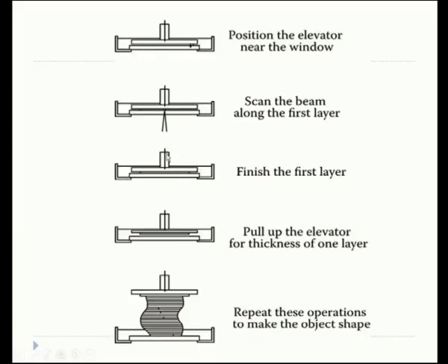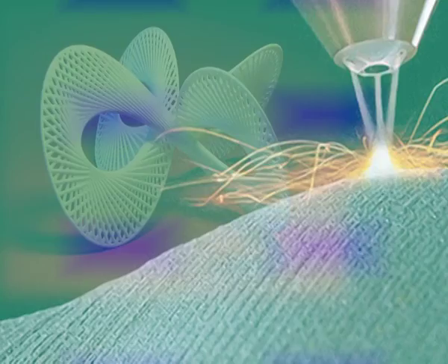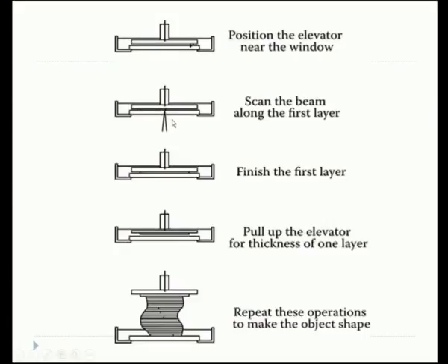And the elevator is going to move upward. You can see the final component formed, which is totally out of the fixed region at the bottom. So how is this achieved? The laser input is given from the bottom side. You can see the two arrows focusing on this point, right? So this is how the laser gives an input. You can imagine almost a photocopier machine. Once the slider moves, you can see the light focusing on it. Similarly, once the input is given from the bottom, polymerization takes place. Can you understand the basic difference between those two? Once the layer is formed, based on the input we are giving from the STL file, it is going to move up.